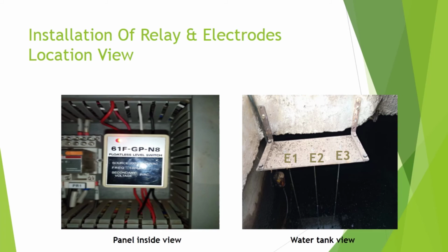Installation of the relay and electrode location view. Yes, in this slide I am going to show you the panel inside view of the floatless level switch relay mounted on the rail. And on the other side, this is a water tank view where the 3 electrodes installation has been done by my team at the site.